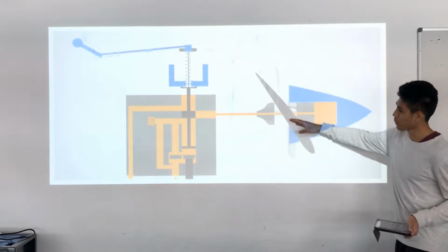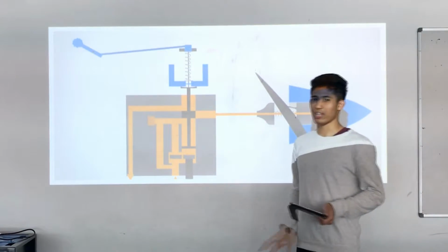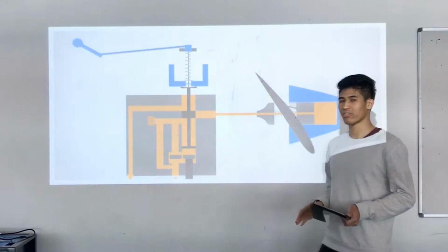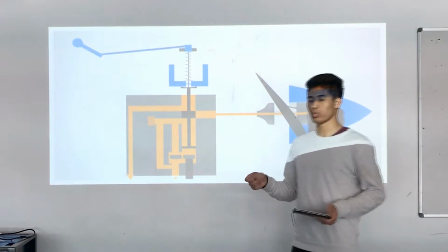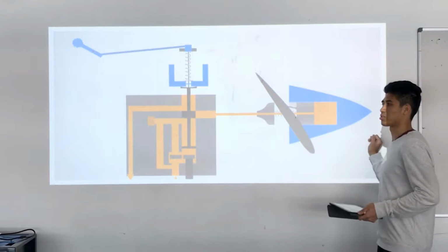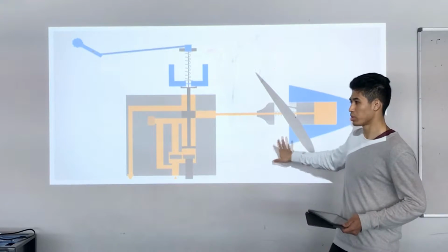Once we coarsen the pitch, this will allow the aircraft to fly at a lower RPM but at a higher speed. So for example, once an aircraft levels off from a climb, it will coarsen the pitch to allow for a slower RPM and a faster cruise speed. And that's one of the benefits of having a variable pitch propeller.